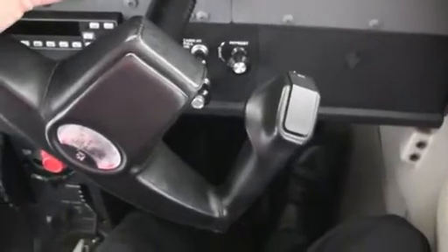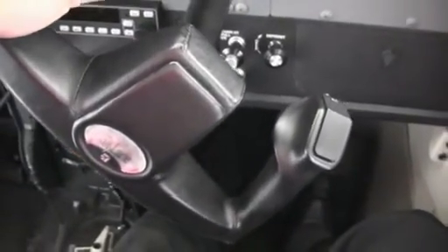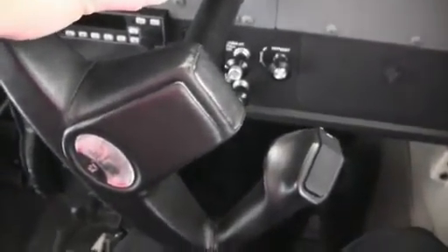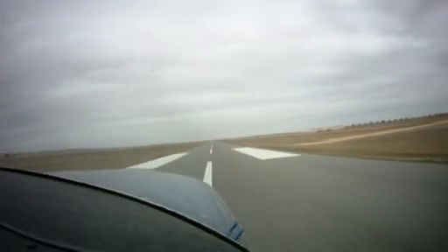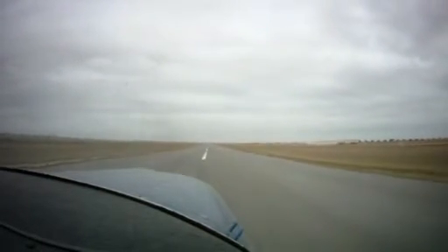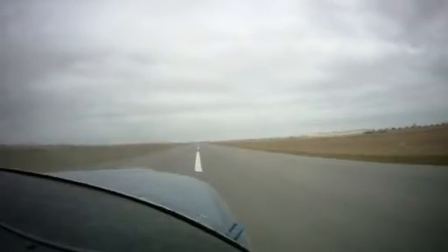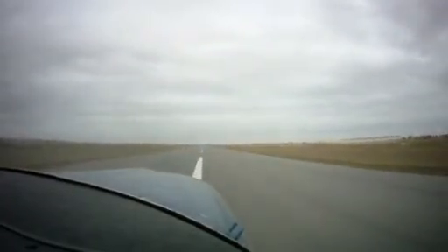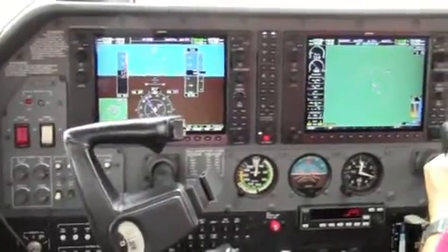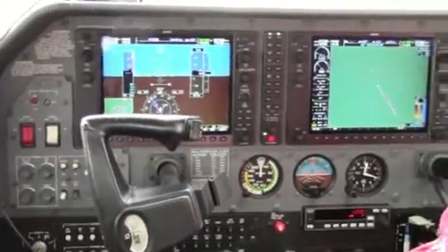In this technique, the drift is controlled with the ailerons and the center of the runway with the rudder. This will continue till the flare and with the touchdown, where we need to continue holding the crosswind correction. It looks very hard, but with the correct practice, you will be able to learn this challenging maneuver.